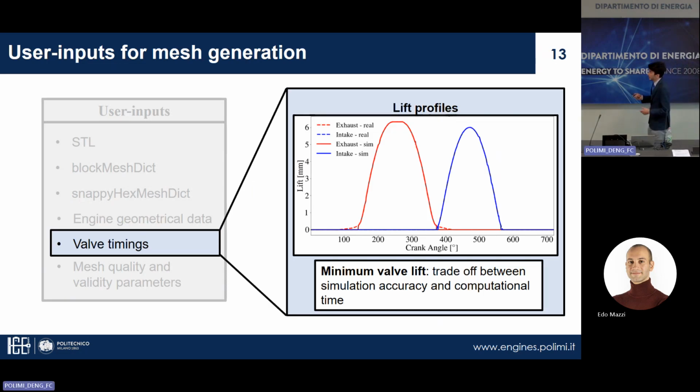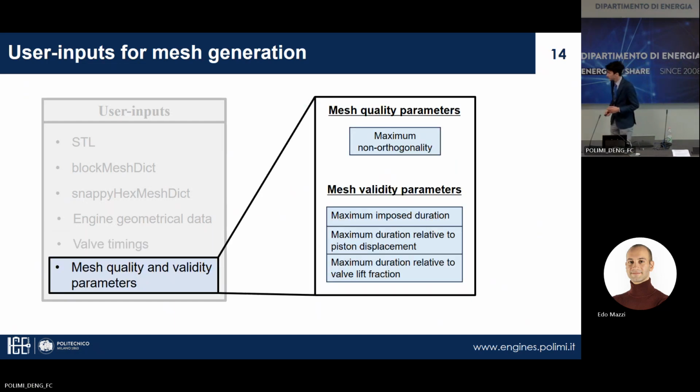The valve profiles, valve lift, both for exhaust and intake, together with the minimum valve lift, which is, let's say, a quite important parameter because it's a trade-off between simulation accuracy, the smaller the minimum valve lift, the closer to reality we get, and computational time, of course.